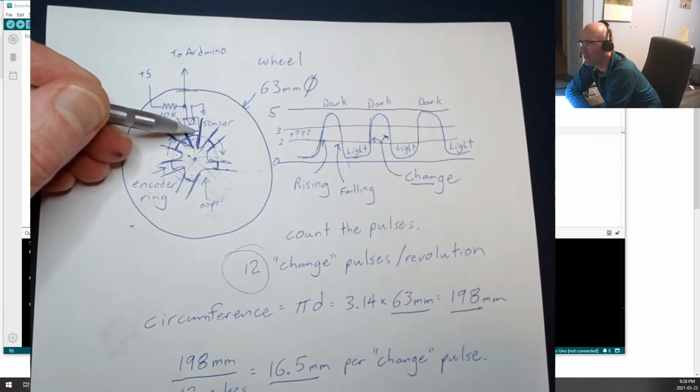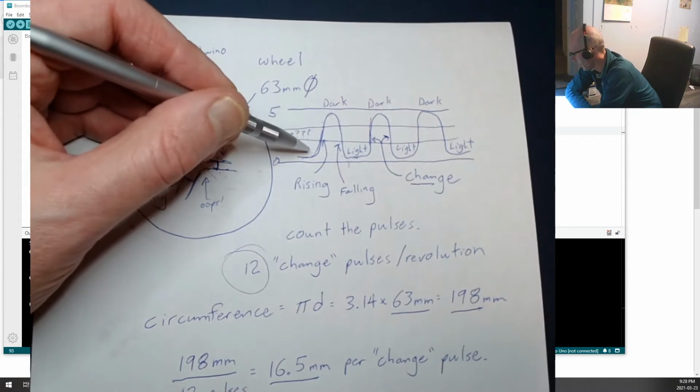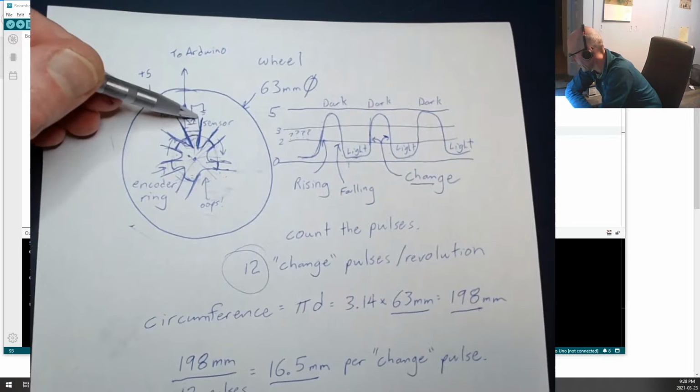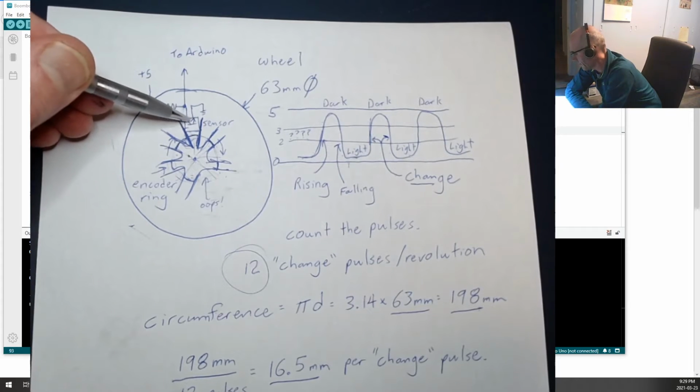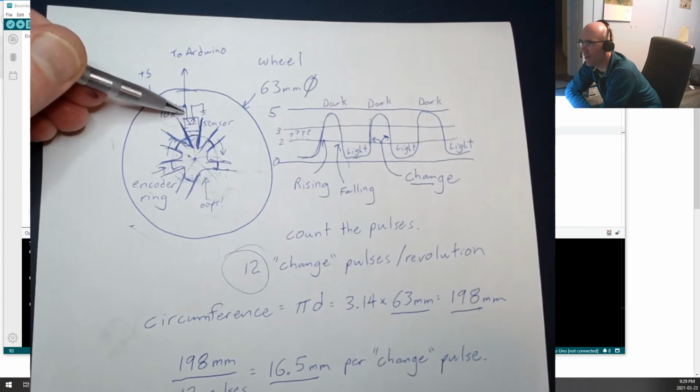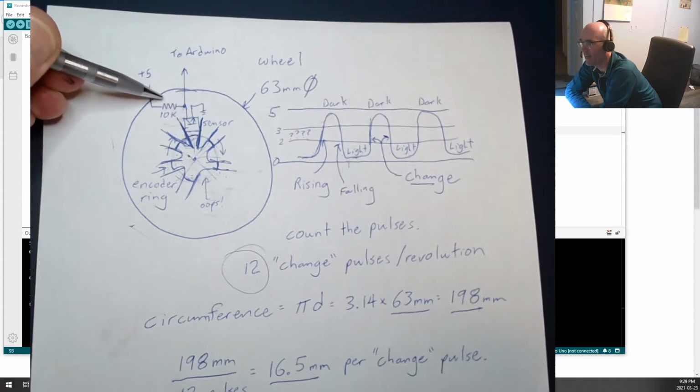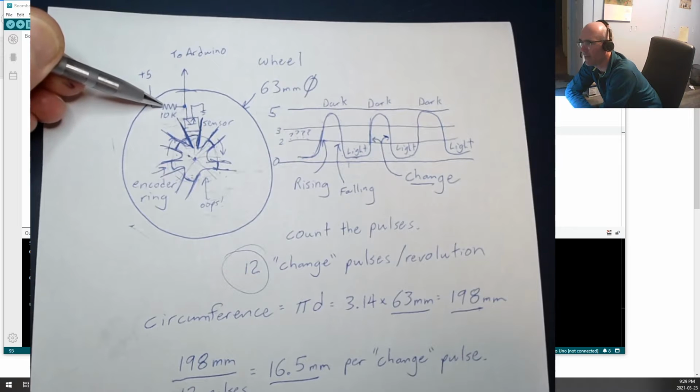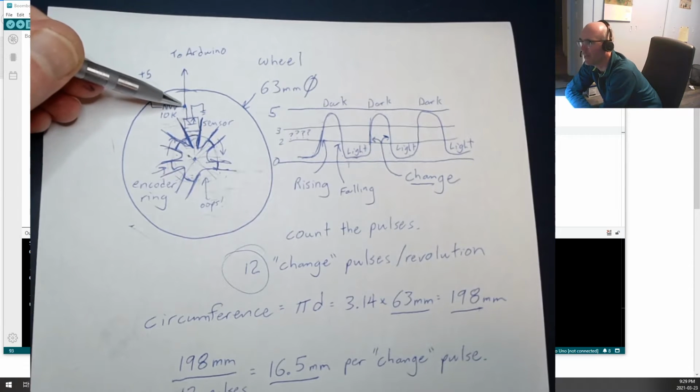And there's light being bounced down here from an LED, reflects off here, and when it's getting reflected into that sensor, it comes in right here and it closes the circuit on that phototransistor because it's like the base. So when the photons come in there, they hit the base and it's almost like there's a tiny little photocell in there that picks that up, turns the transistor on, and allows electricity to flow down through here. So you've got +5 on this side.